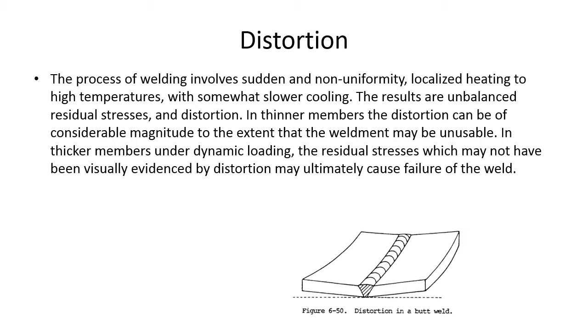So what's that telling us? That's telling us that if we have thinner materials, and I'm going to throw out a number here, I'm not exactly sure where the thin and thick borderline is. Maybe it's kind of a zone there. But let's call it 3/8 of an inch, 10 millimeters. I don't even know if those two are equal, sorry if my math isn't great on that one. Between those two numbers, and thinner, the material is going to buckle, and you're going to probably be able to see the problems with the buckling and whether or not the distortion is making that part usable or unusable.